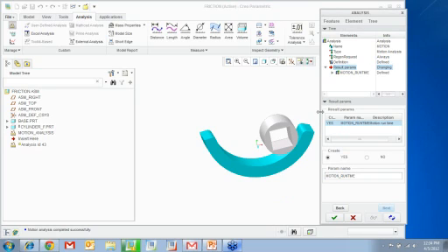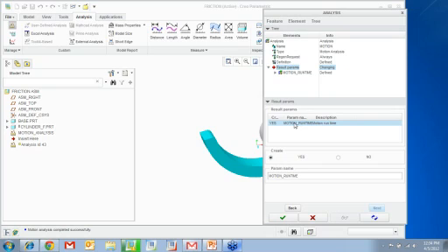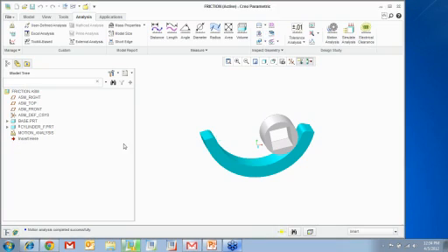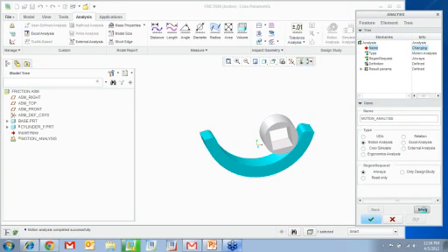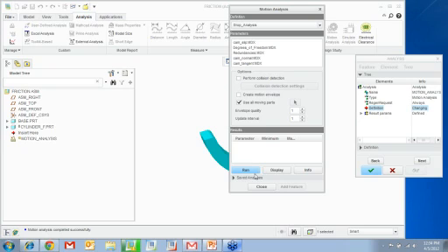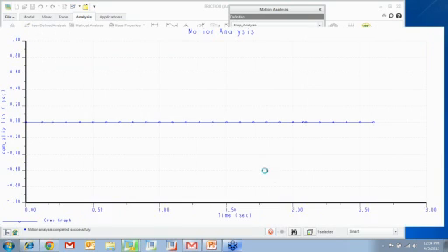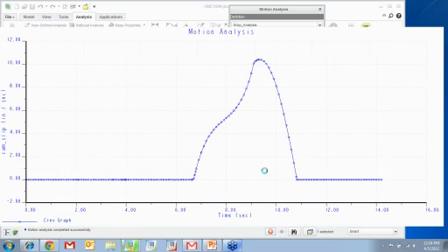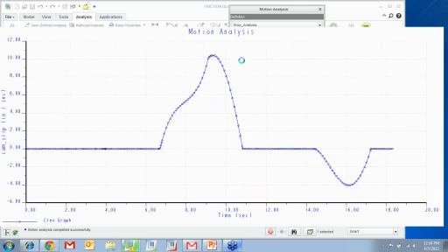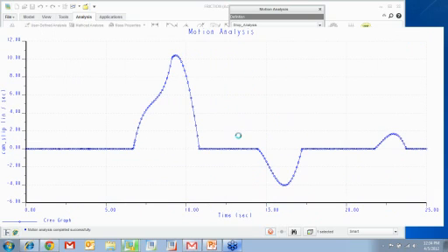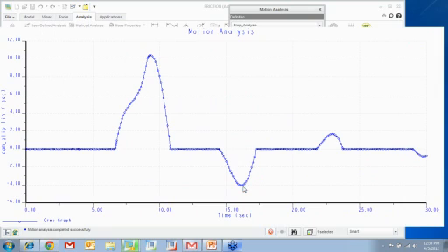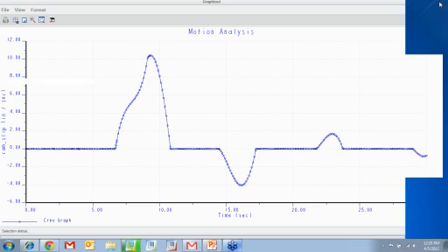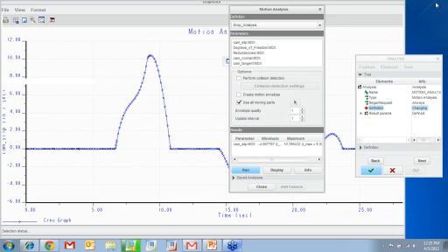So you see different parameters that you can create. Okay. So that's how this particular analysis was created. Okay. Motion analysis. Here are some of the parameters that we have. We're going to run this, and it kind of shows you the up and down. So with respect to performance monitor, now let's say we want to monitor the cam slippage maximum value and the minimum value, right? So now I'm going to say done.